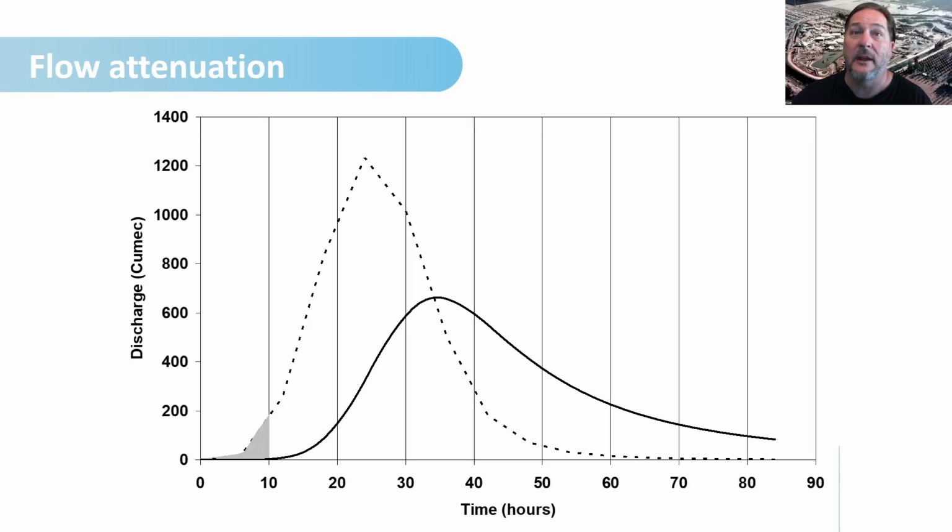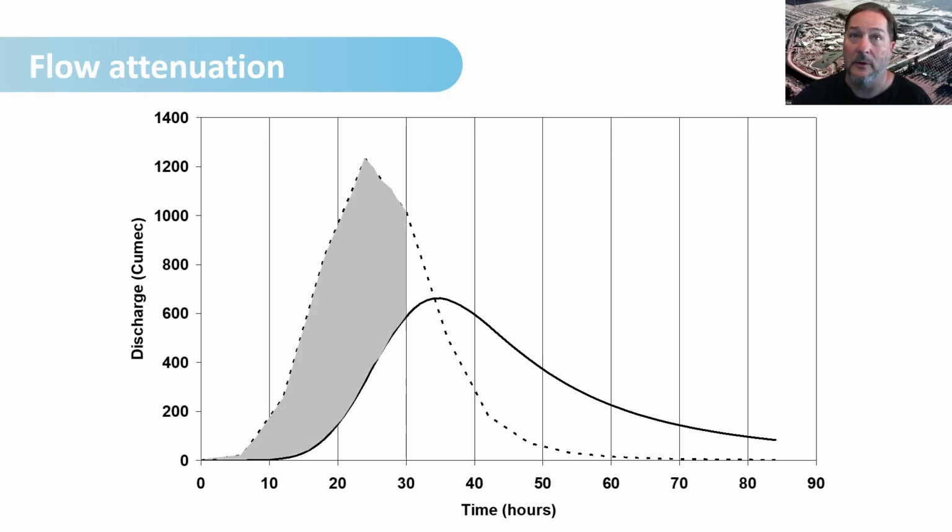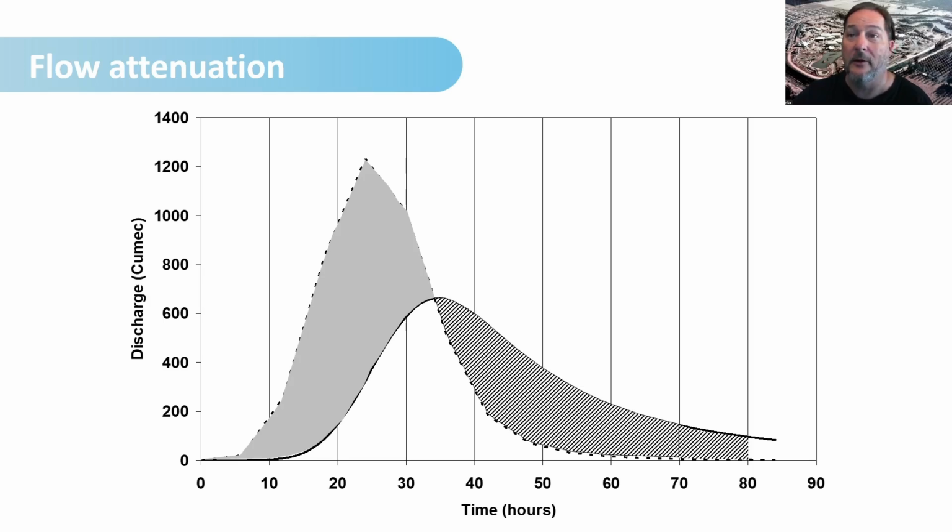So in this case, for example, if you had a hydrograph coming in that peaked up at 1200 cubic meters per second, again, the volume of water that's coming in could be the same. That's the area under the curve here. If this area matches this area here and all you've got is attenuation, then sometimes what happens is that attenuation will occur where you've got your internal boundary condition, and what's actually moving downstream could be half the flow rate that you actually wanted to move downstream.